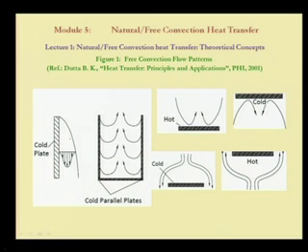So, what will happen? Because it is a cold plate, not a hot plate, fluid elements coming in contact with the plate will become colder, and as they become colder, they will try to move in the downward direction. So, other fluid elements from the environment will try to take up this position, and these fluid elements at these locations are at a higher temperature. So, this is the velocity distribution that takes place.